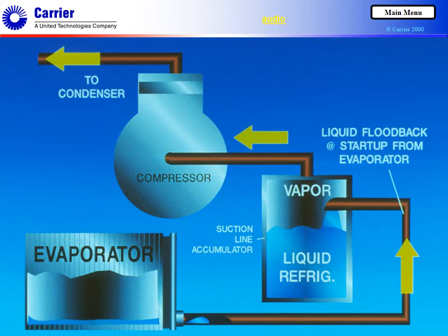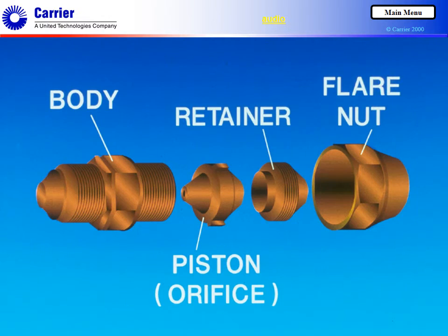Additionally, special care is given in charging systems that make use of a capillary tube. An alternative design to the capillary tube is a fixed orifice. It accomplishes the same thing as the capillary tube, but in a compact and rugged assembly. A major advantage of the fixed orifice over a capillary tube on heat pumps is that the orifice can be built into a check valve that allows reverse flow with less piping and parts than are required for a capillary tube. It is like the cap tube in three major ways.